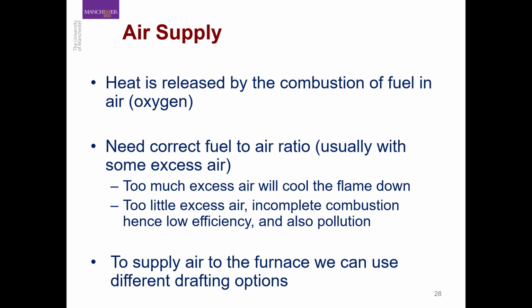On the other hand, if you have too little excess air, it means you are not providing enough oxygen to complete combustion, and as such you are going to have a range of byproducts, for example, instead of carbon dioxide you are going to produce carbon monoxide, and again, because of incomplete combustion, you are going to have low efficiency of the furnace process. So a correct fuel to air ratio is really important.